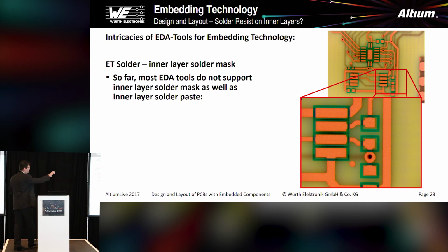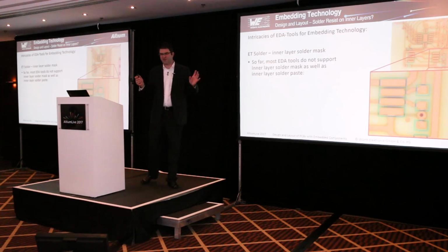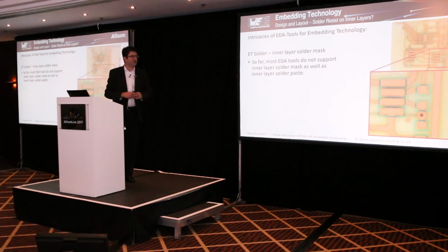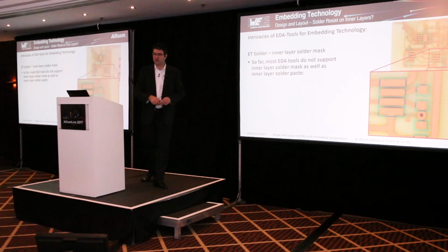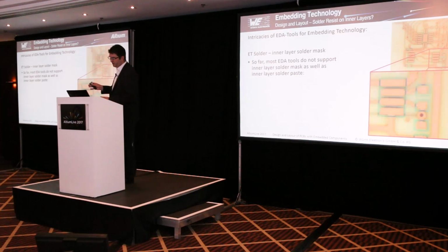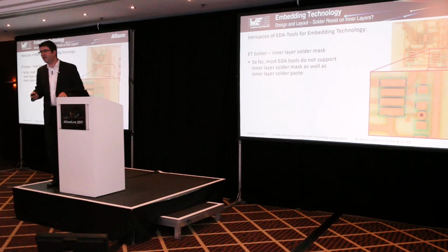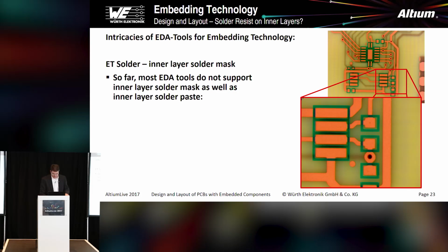So this is what it actually looks like from a manufacturing board. Here you see the copper traces, and those small frames surrounding your pads. These are 100, 150 micron frames, 75 micron even when space gets very tight, but nothing else. The remaining part is still the metal. We do not want to have more solder mask, because reliability will be much higher if we just use the solder mask in the area where we need it, and the delamination risk is reduced by a lot.